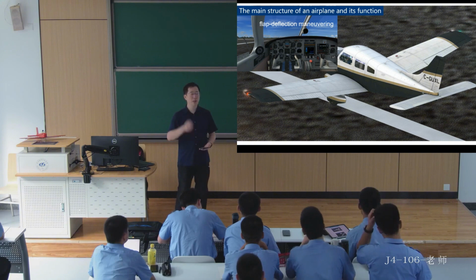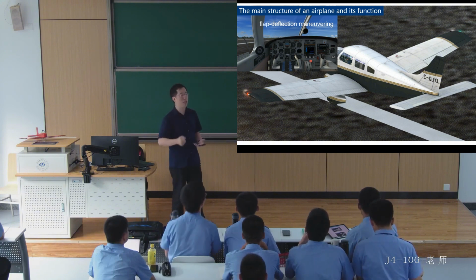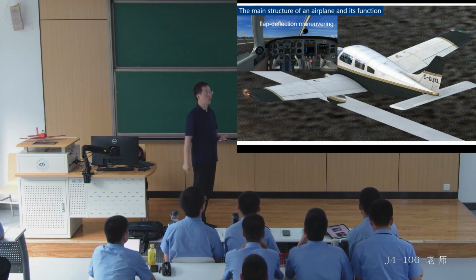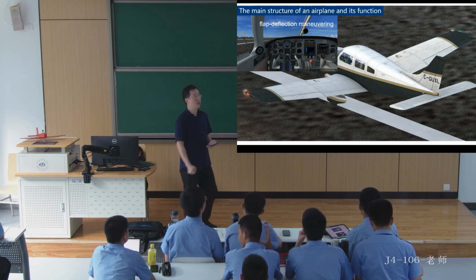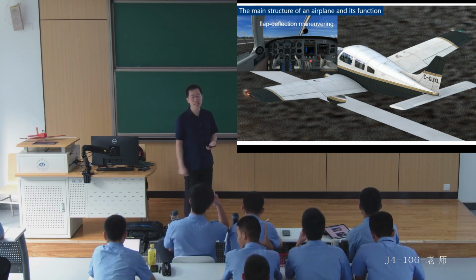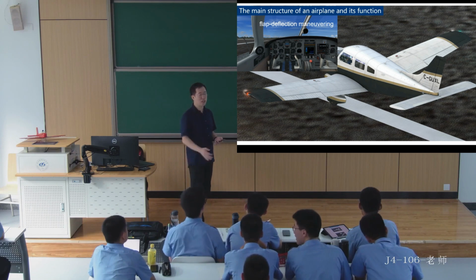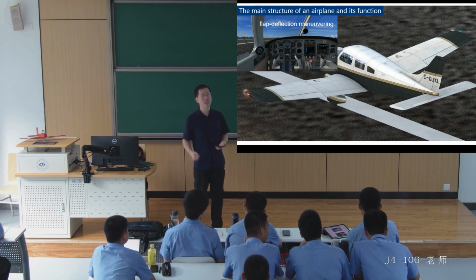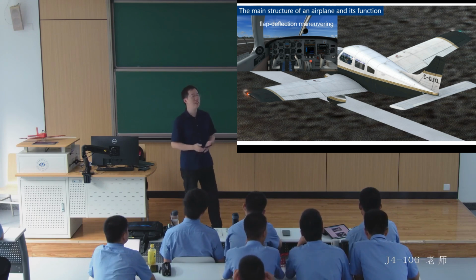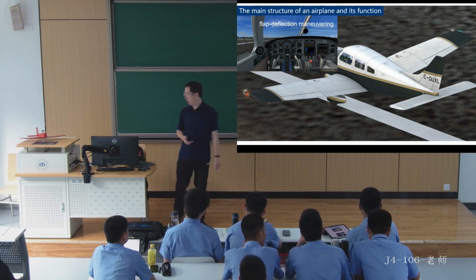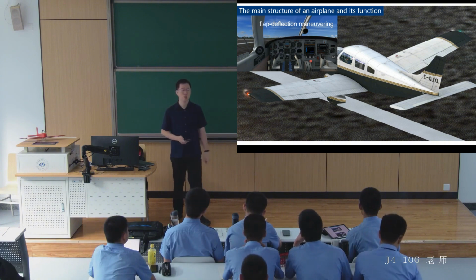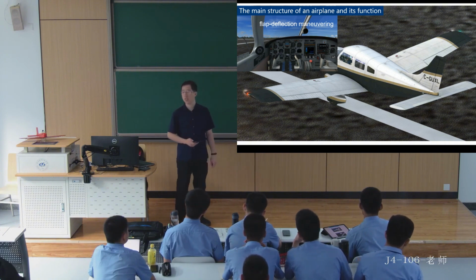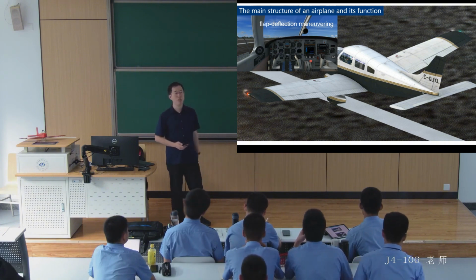So, for the PA-28 aircraft, its flap operation is quite interesting. It doesn't use electricity. Instead, it's manually operated by hand. In this way, when you pull up, it's like engaging a handbrake, which corresponds to the process of lowering the flaps. The PA-28 aircraft has flaps with settings of 0 degrees, 25 degrees, and 40 degrees. These three angles correspond to different position selections.